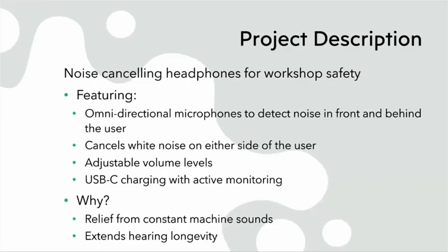The purpose of our headphones is to be worn in workshops that have consistent loud noises, and we want to extend the longevity of a person's hearing. Our design features 4 omnidirectional microphones that detect noise and process signals in front and behind of the user so they can hear alarms and instructions, but they cancel the noise on either side of the user to protect them from that.